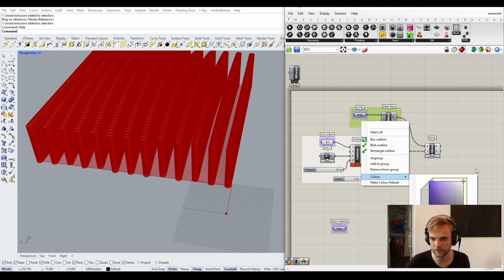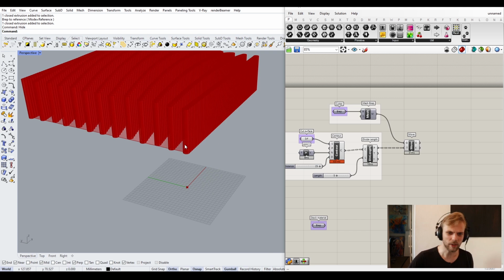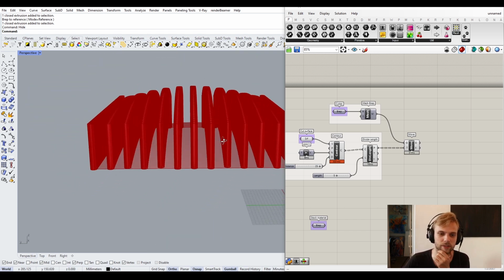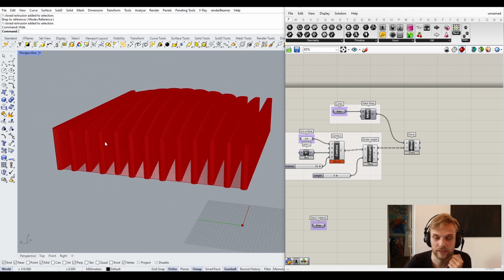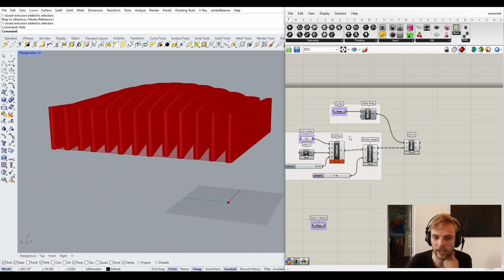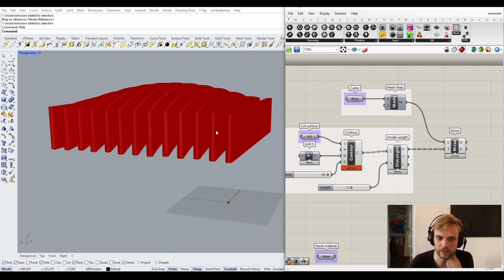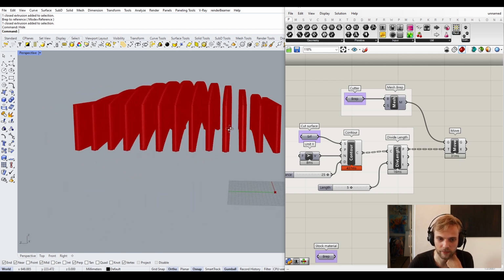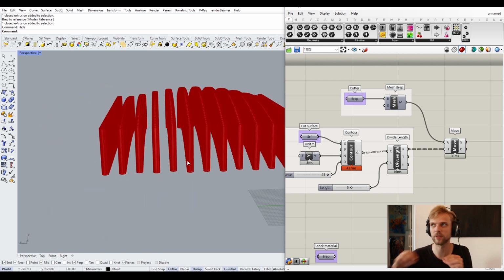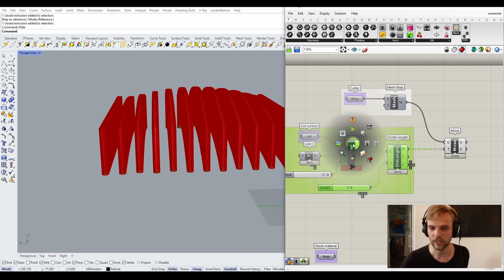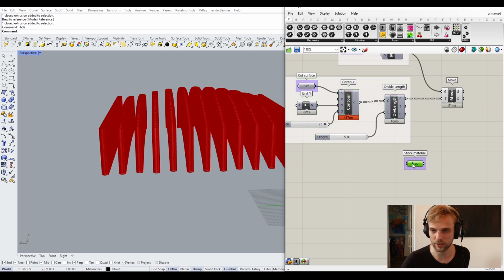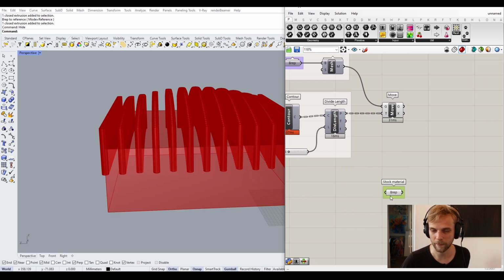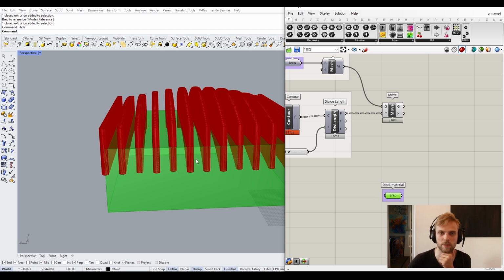Perfect. Okay. So now what I want to do is use these tools. I don't care about the surface anymore, by the way, because I have the cutter placed on each of these points, right? So I am going to remove from the stock material with these cutters and see what's left.